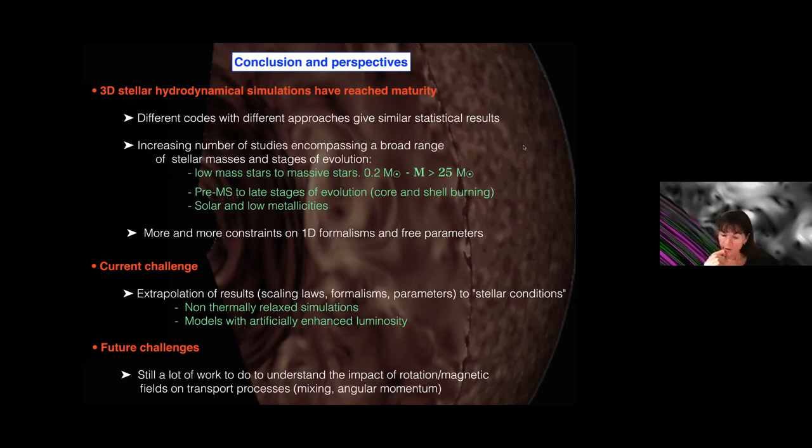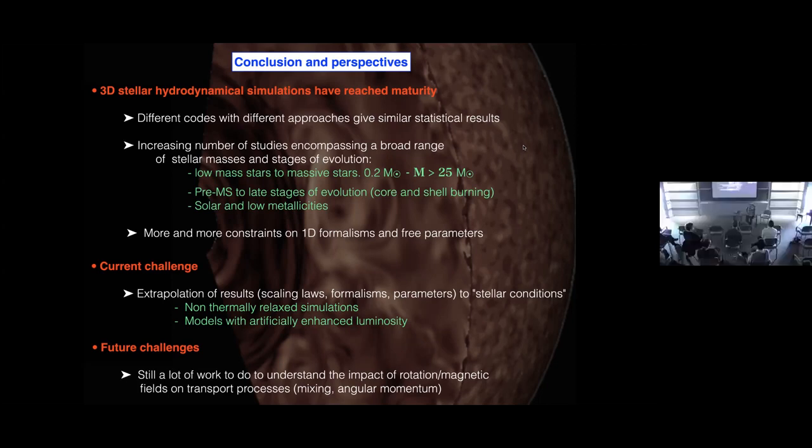Some of the codes actually use an artificial viscosity where they can more or less control the Prandtl number, for example, but it also depends on the numerical diffusivity of their own code. So it's not a fully controllable parameter, and therefore you have to be very, very careful there. I don't know whether I answered your question. You did. Thank you.